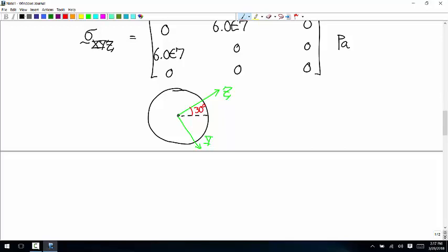We want to rotate it. We want to re-express this tensor in a coordinate system like this, where that's the Z-axis and that's the Y-axis. So what's the rotation it takes to go from the capital to the regular one? Right. Yeah, so you can rotate this clockwise 30 to make it line up there, and then it's 180 from there. So minus 30 plus 180 is 150.